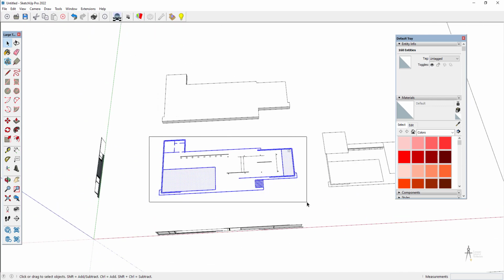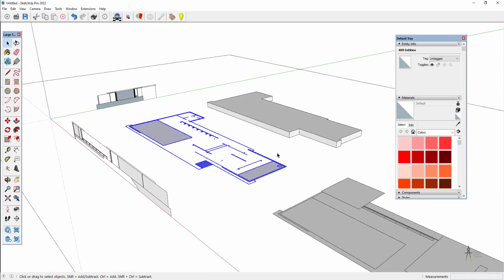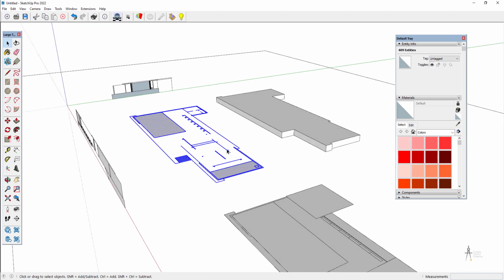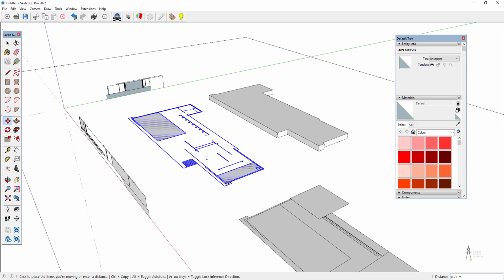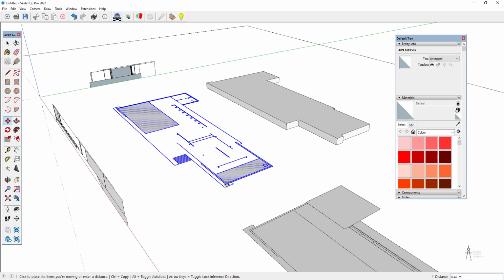I'm not triple clicking as we learned in the first exercise, because there are things that are out of the object. So that's why I find the floor plan view. Once you've selected it all, you click on move and find a reference point, this one for example.